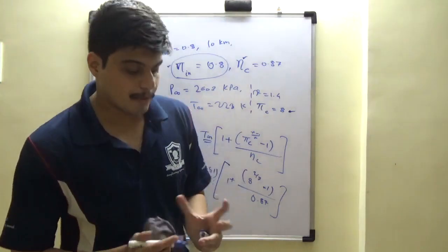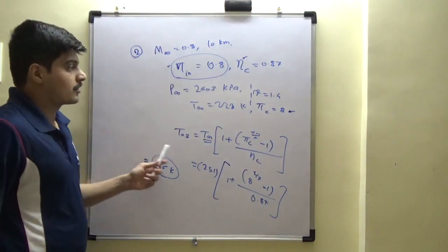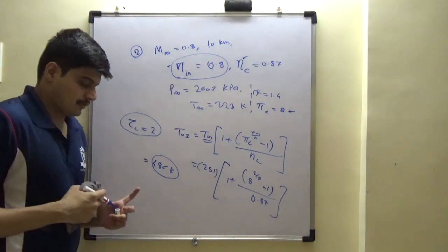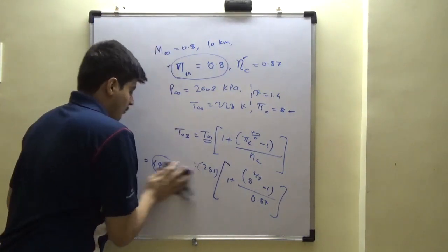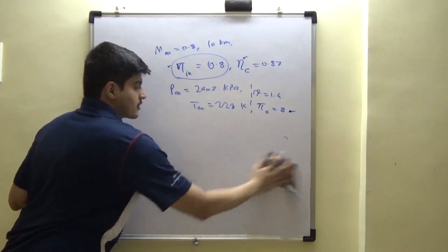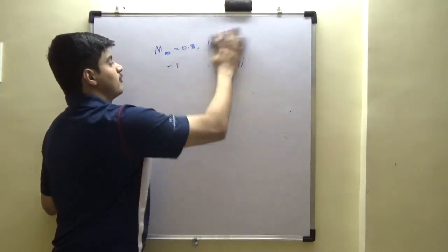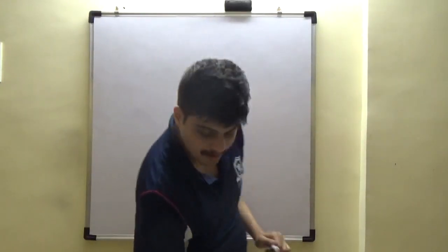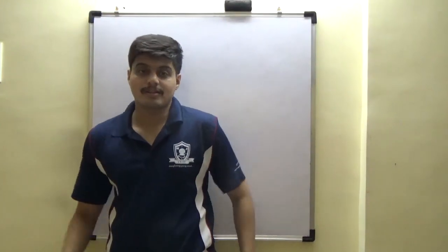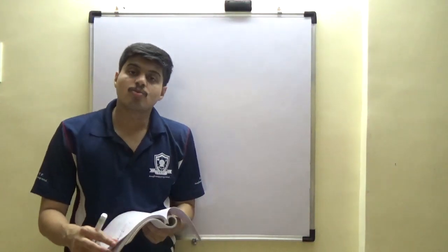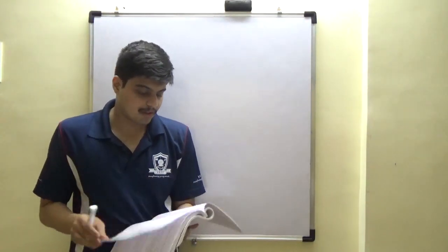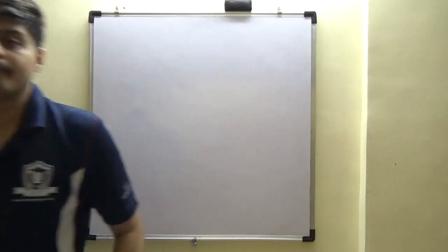Now see the rise in temperature. That is important to analyze. Compressors for pi 8 is giving you tau of about 2, which means higher the compression, more will be the temperature rise. Now this 400 Kelvin hot flow is going to enter my combustion chamber. Fuel is added, turbine is rotated through this, nozzle expands, and that's how the components match. As an undergraduate student of propulsion, you should have these concepts very, very clear in your head. How each component talks to the other component. Okay?